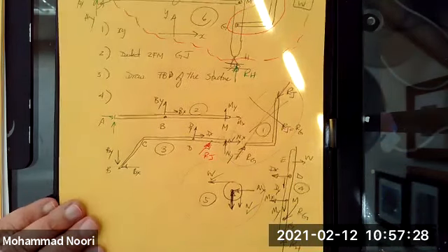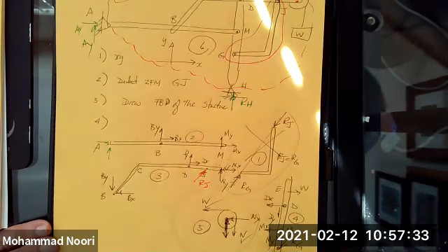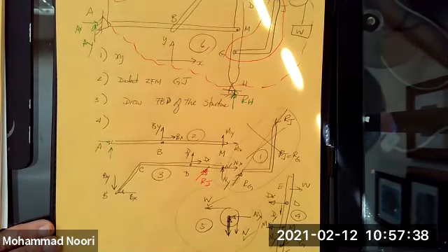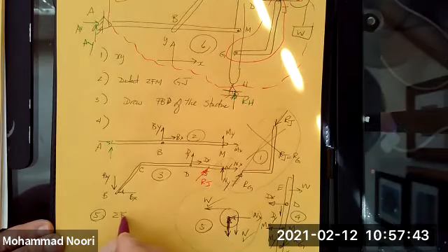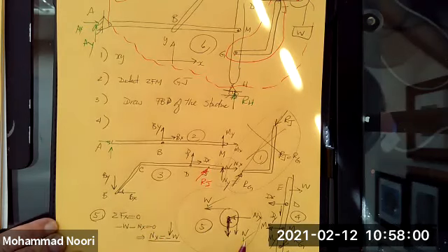So that's out. So of all the 5 more that you have left, this is the one with 2 unknowns, right? So I will start with number 5. Write equations of equilibrium. Summation of forces along x equal to 0 gives me negative W minus negative Nx is equal to 0. So Nx comes out to be negative of W. That means the assumed direction for Nx is wrong.